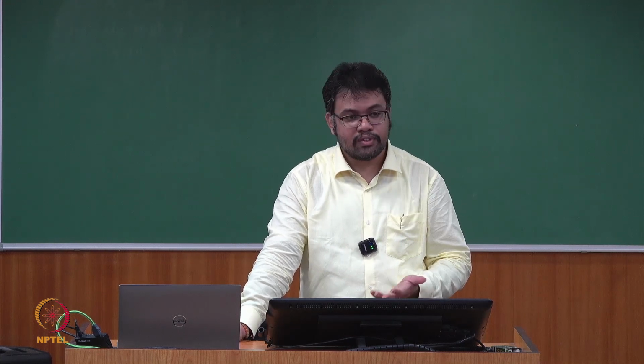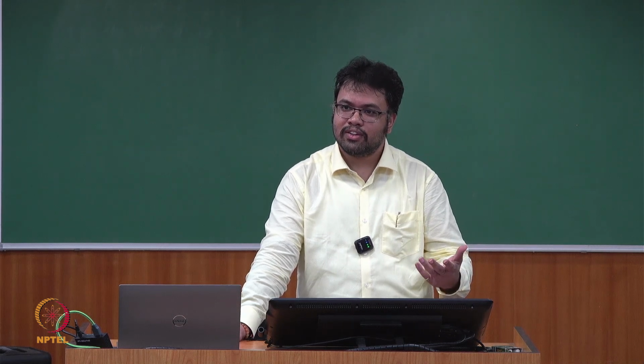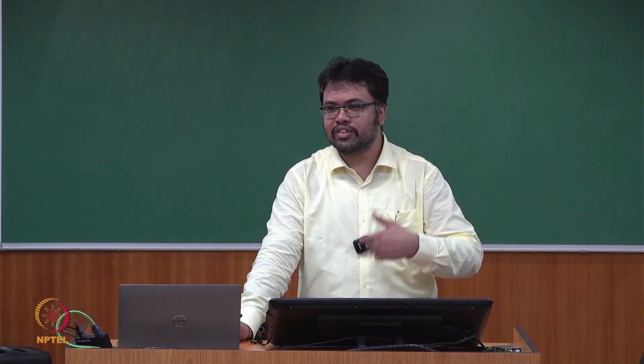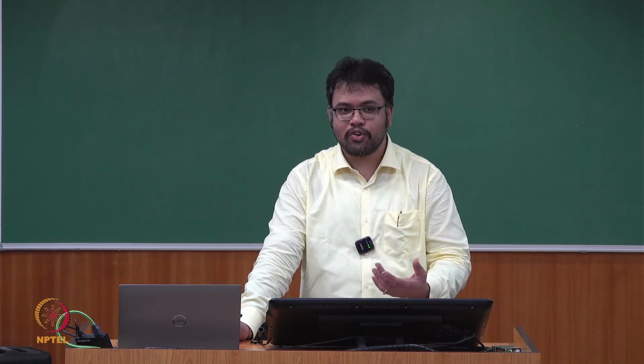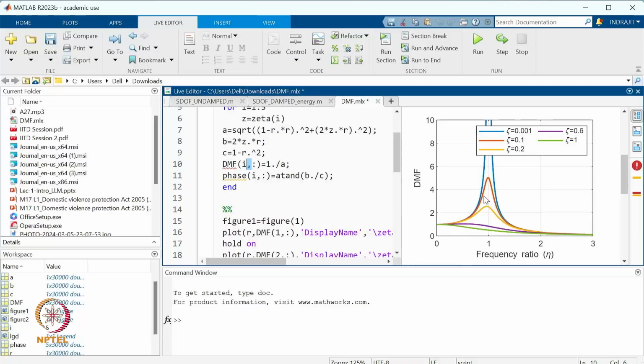start oscillating. Think of it from real life. Like you are also some sort of similar guy. Once you come to that environment, you can feel a resonance. Your performance will become very, very productive. So you can also see that same thing reflected in the dynamics of the system. Once the system's natural mode of vibration and natural frequencies match the excitation frequency, the structure starts oscillating much more vigorously, which is known as resonance. So that shoot-up is due to the resonance, and that is the resonance condition.